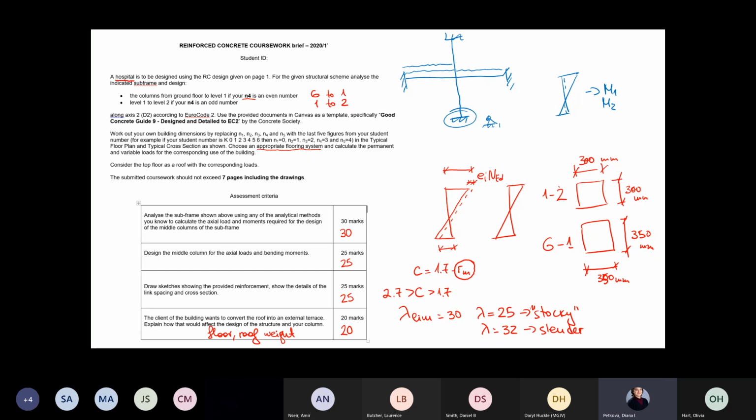Let's use this assumption so that again you have two different solutions or two different setups for the location of the column, for really the uniqueness of your solutions. If that's the case, though, you'll have a diagram that will have only M2. So this diagram obviously will be slightly different. For your group design, because you're probably going to have a pile foundation or a much stiffer foundation, the fixed support probably is fine.